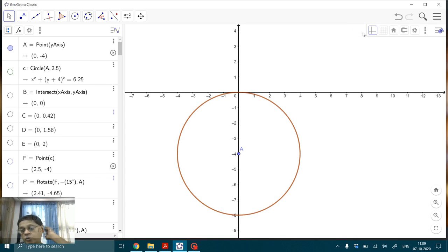So as before, I have located the center of the cam at -4. Now it is showing in centimeters instead of millimeters. So 40 mm, which is -4, and then I am going to draw a prime circle. So this is 40 mm radius. So the x-axis is basically tangent to this, and of course in the original radial case, the follower would have been going up and down like this, but in this case it is going to go at a distance 25 mm to the right.